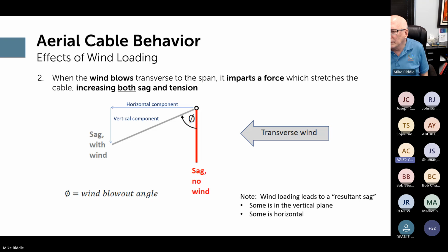So it's interesting to know that you mentioned the error in the sag calculations. Once we issue a stringing chart for construction, we provide tension and sag at different temperatures, and in the field we keep some margin for construction errors. But once we check it after installation, with the contractor checking with a dynamometer, the sag almost matches the calculation we provide. Tension and sag are both almost matching, not 100%, but they are matching. Well, great.